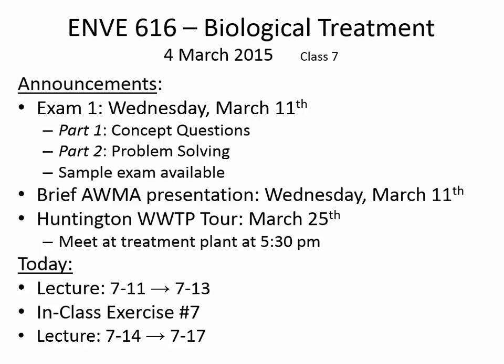Let me ask you this one, part E. What's the purpose of recirculating sludge from the secondary clarifier into the aeration basin? Once they're recycled and back into the aeration basin, they've been deprived of oxygen and they're hungry, so they're a lot more efficient at that stage than they were previously going through. All right. That's definitely one of the important benefits of recirculating after it's coming from the bottom of the clarifier.